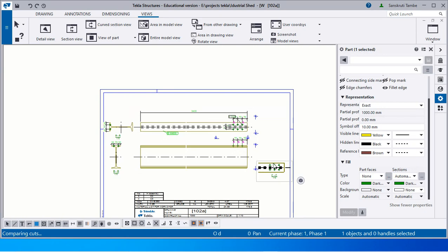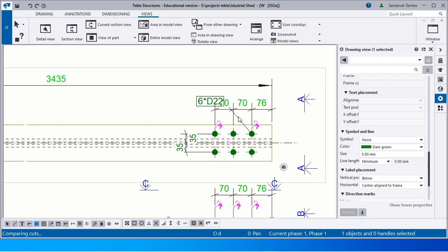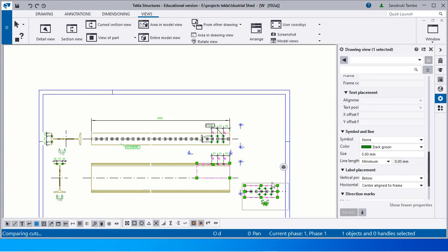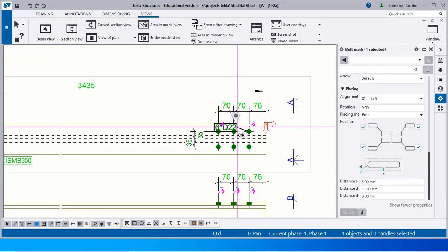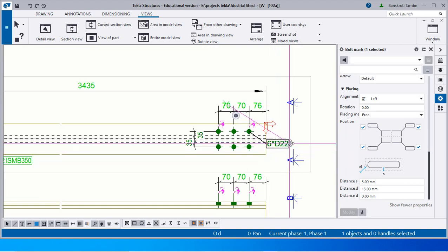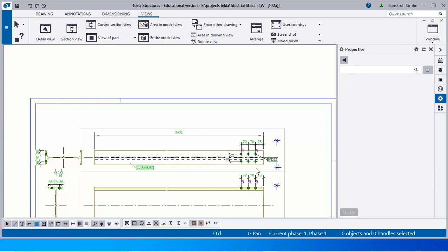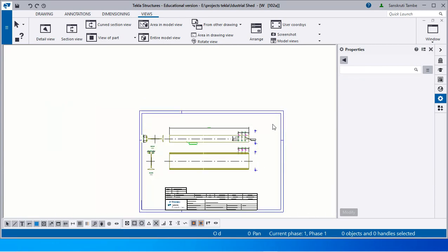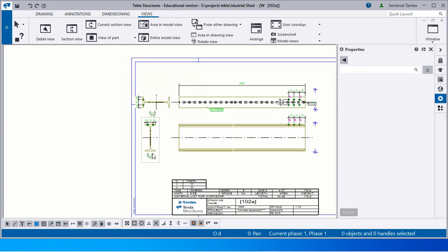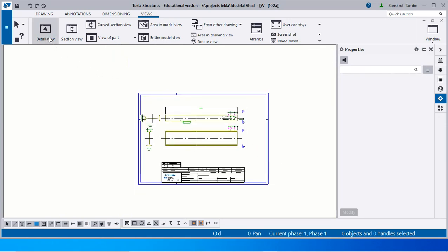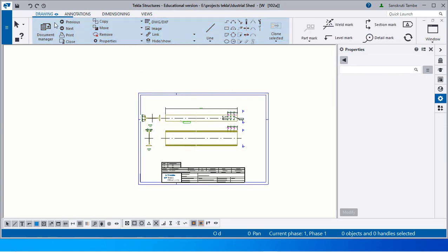This is shown over here. Okay, as we have already given the dimensions, there is no need to set a separate one. Okay, then the part mark for these holes, 6 of 22 mm diameter. So like this you have to prepare the single part drawing for the columns. Okay, then next going to this document manager,